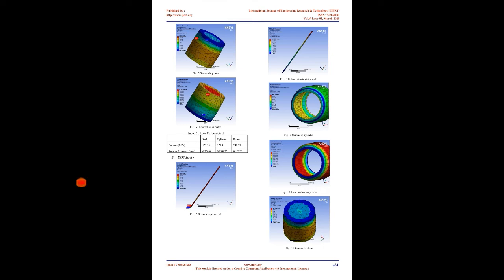The bursting stress can be referred to as the amounts of hoop stress and longitudinal, axial, stress that are produced in the wall of the cylinder when subjected to internal and external pressures that may cause the material from which the cylinder is made to fail. This happens if the hoop stress exceeds the tensile strength of the material.